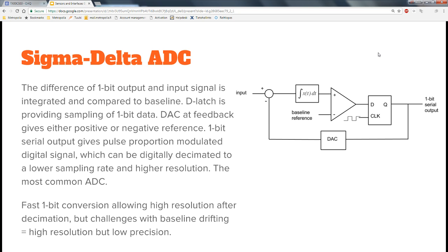And sometimes nature is against you, but sometimes it actually works for you. Another thing about sigma delta is that because of the decimation, you actually start to cut the higher frequencies. So very high frequencies you cannot detect with this one at all.